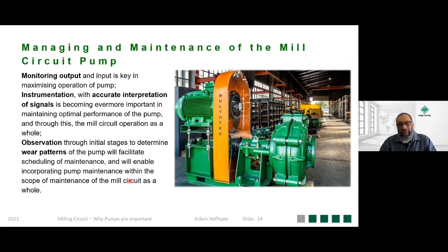But now the important thing is, remember, we've discussed the adjustment of the impeller. You can still get maximum life out of the lining of the pump, and we want to promote that as far as possible. So simple things like adjustment, little things that can still be taken care of, promote life with the existing components of the pump. Yes, there will come a time when the wear rate has exceeded its bounds, and then you need to overhaul the parts that need replacement, etc.